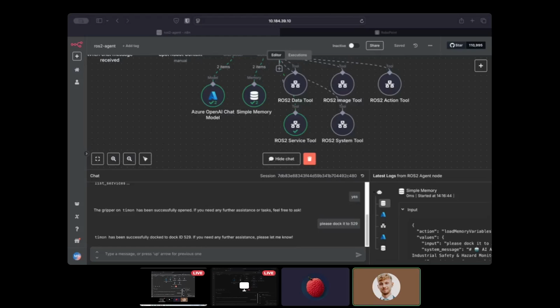All right, so the question: which manipulation module does Spot use in this setup? As explained before, I'm using the robot's manipulation API. From Boston Dynamics, there is an SDK which has a pretty good manipulation API, so I didn't have to build anything on my own. I didn't have to use MoveIt or anything else, like Isaac ROS FoundationPose or Isaac ROS CenterPose. But when using other robots which do not have manipulation APIs out of the box, this could be a very good starting point to build your perception and manipulation pipelines.